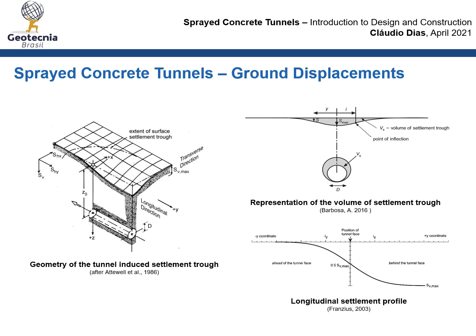In terms of longitudinal direction, we can see that at a certain distance from the tunnel face, the settlement starts to build up and stabilizes after the tunnel face has passed. Typically, these distances are plus or minus 2 diameters.